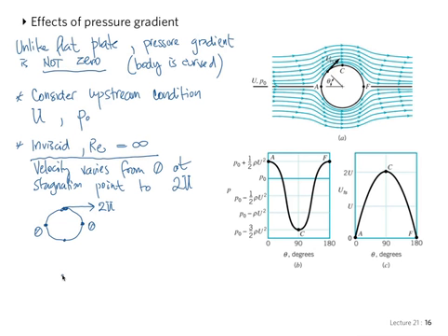So there's quite a bit of variation in velocity, and therefore, by Bernoulli's equation, since this is inviscid, there's also variation in pressure. The maximum pressure is, as you know, the pressure at the stagnation point.